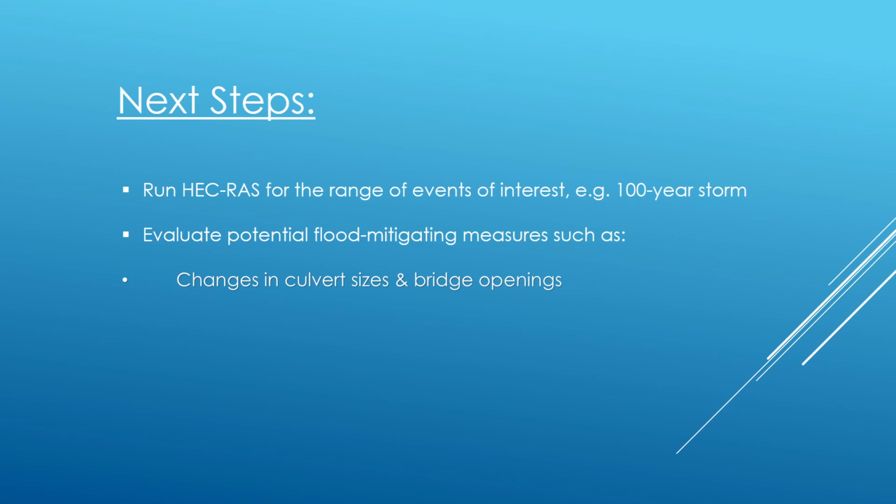such as if you're going to change culvert sizes and bridge openings, you cannot simply transfer one problem from one area to another and generally get a permit for what you're looking for. You could look at changes in embankment heights, and perhaps you could get even more creative and add flap gates that maybe keep the tide out.